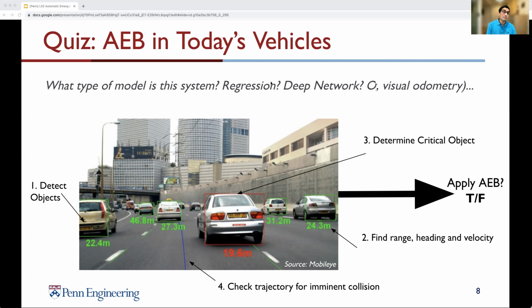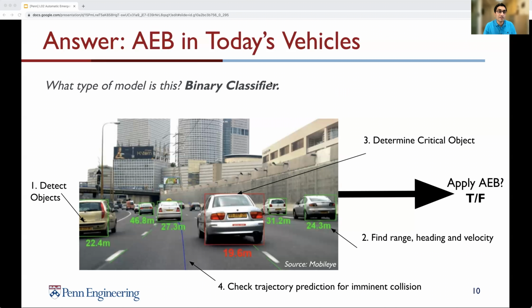So how should we go about building this critical object detection and evasion system? We could have a camera to detect and classify objects, and also detect lanes to estimate their heading. We can track objects across multiple frames to estimate their velocity and acceleration. And with the radar, we can estimate distance. Then, fusing the camera and radar inputs, we can analyze each vehicle's potential for a crash. But perhaps there is a simpler way to get started.